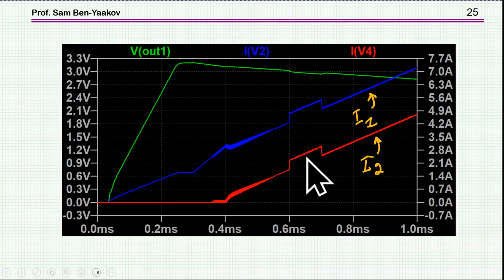And you see it here, and you see very nicely that the dynamics is pretty good, that both of them are reacting very nicely. And here we have the current going up. This is the difference in the current, and we see the drop in the voltage, total voltage. Of course, when you have the step, there is also a drop here in the voltage, and this is the slope, this is the droop, in fact, due to the fact that the internal resistance of the power supply now is higher due to the internal feedback from the current.